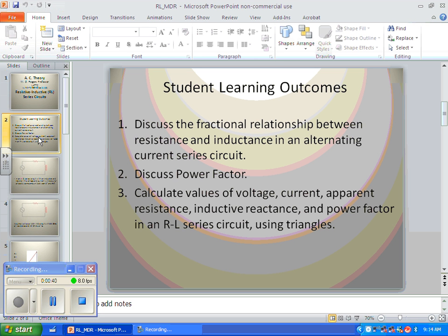Now, the textbook that you did homework out of, I understand it directed you and you did Pythagorean theorem. And I understand that. That's fine. Pythagorean theorem practice is fine. But that's not how we do it here. Because if you calculate the impedance of a circuit by Pythagorean theorem, that's fine. You've calculated resistance, inductance, and impedance, but now you want to do a power triangle and you have no idea what angle you have for a phase angle. We'll talk about that in a few minutes. So it leaves you without the information you need to go to the next step.